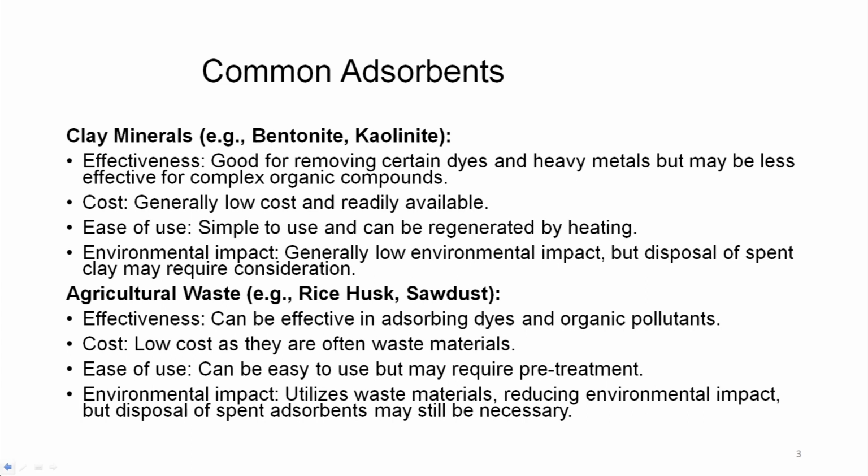Clay mineral, bentonite or kaolinite. Effectiveness: good for removing certain dyes and heavy metals, but may be less effective for complex organic compounds. So, clays have certain areas of specificity where they work on certain dyes and heavy metal removal.